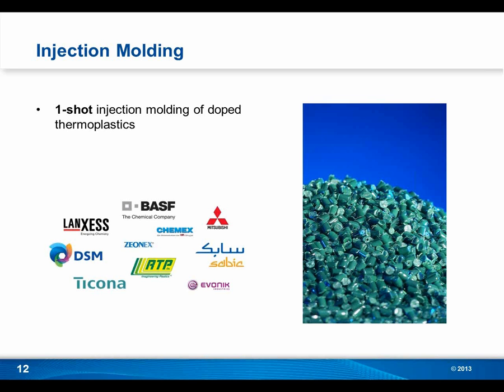And then, Stefan, I actually want to ask you a little bit more about what are some of the types of plastics that are available in LDS grade? Yeah, in LDS grade, there's a lot of materials available right now, and it stretches the entire bandwidth. Anything from very commonly used PC/ABS materials for many consumer devices over to nylon grades that are often used in automotive type applications, and then we see a lot of LCP or liquid crystal polymer type grades in micropackaging and medical applications. So again, pretty much the whole spectrum's out there. And again, it's reputable plastic resin manufacturers that create their particular materials in an LDS grade.